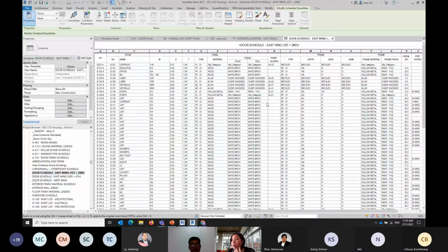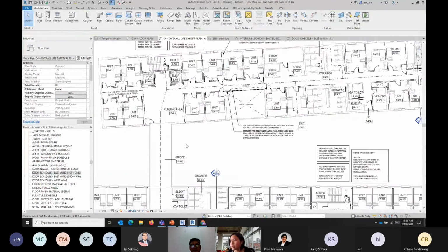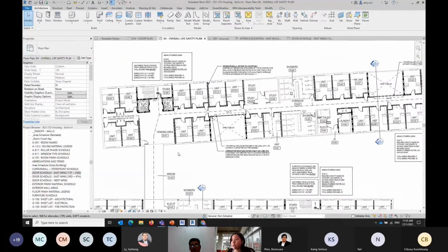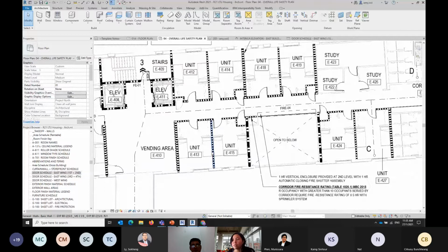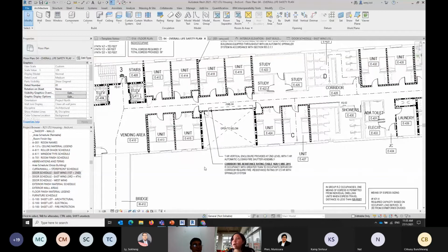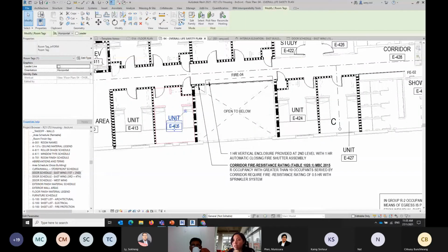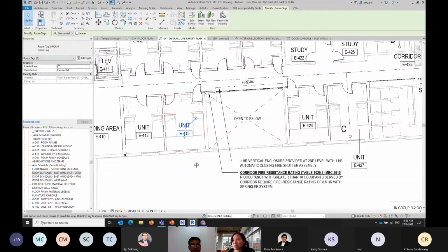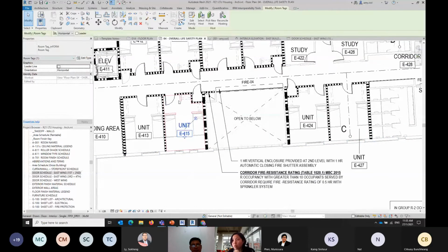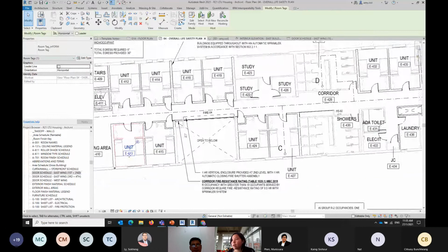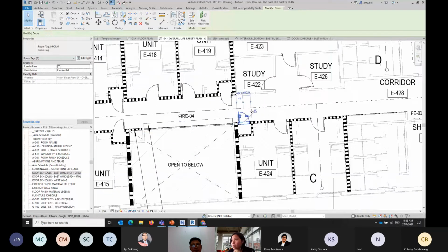And from there on, you can actually also do different kinds of arrangement or layout that you need on this schedule. So I won't spend too much time right now, but what you will see now is that creating different floor plans is really, really easy. And all these things that you see over here, these are tags. What tags means is if the room information changes, the tag will also change with it. And over here as well, you will see these doors.